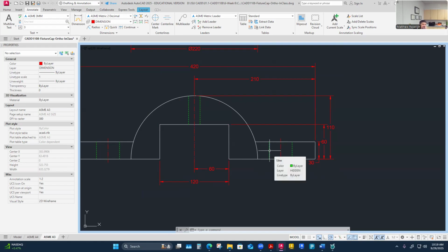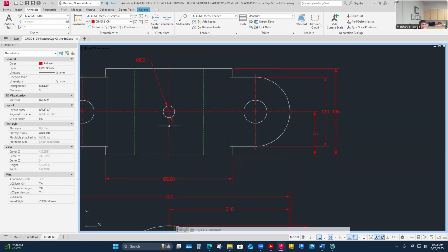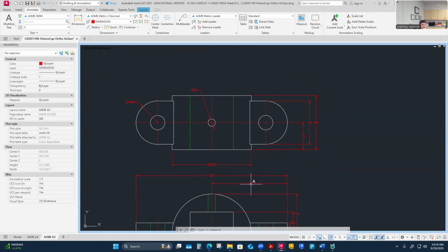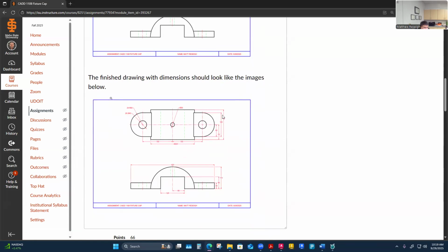And I kind of think to myself, do I need those, or do I just need how far it is from center out to there, which I've already captured with 210? So I capture its size by saying it's 210 from center out to its edge. So this one now starts to function as a size in a way. Let's see if I've added anything else that captures that size. If I look down here, I've got 60 and 75, 120, 150. Yeah, these ones are going to come in when I start thinking about the holes. But really, I didn't even add any sizes that way.